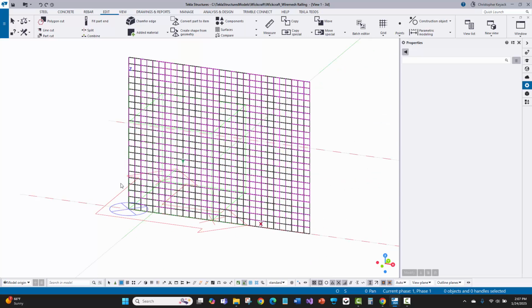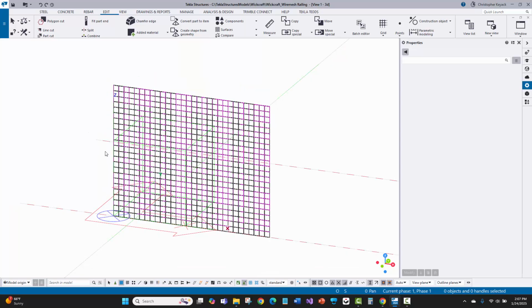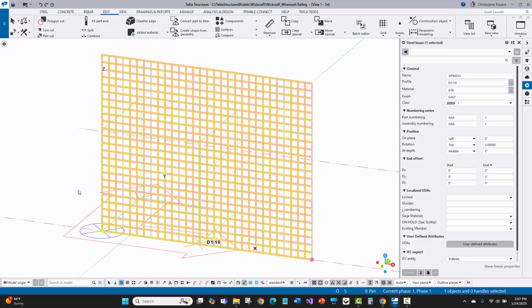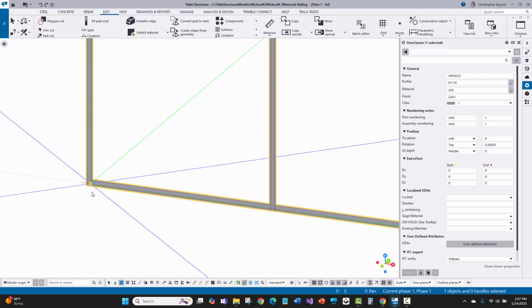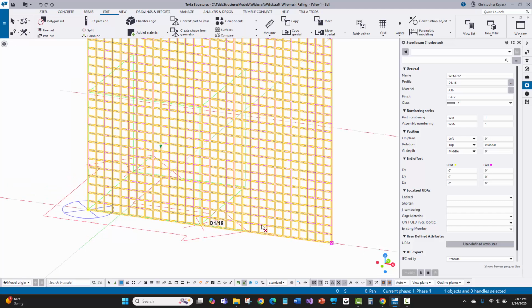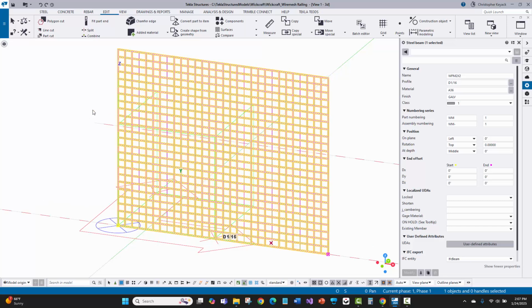Now I intentionally modeled this down here near the origin and in the positive x-axis, so that I could turn this into an item. When you create items of objects that are created natively in Tekla and you don't export them to an IFC file first, you have to strategically think about how you're putting that part in the model. If you use a beam object, I usually do the part add to the object that I want the item to align its picking points and its coordinate system to. That's why I picked that bottom horizontal bar there. It was also because, when making a shop drawing of this, it would draw it horizontally. But I just wanted you to understand that there are a couple of different strategies to making items.